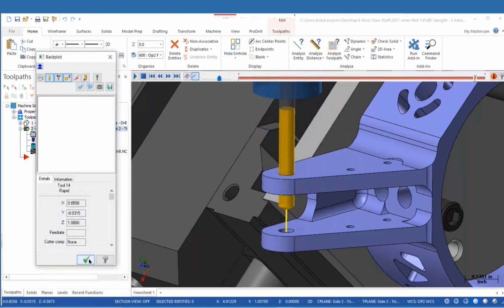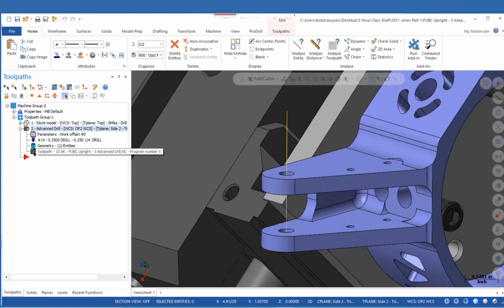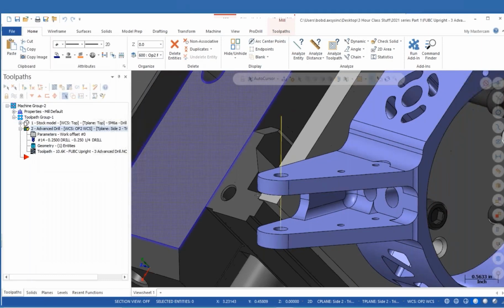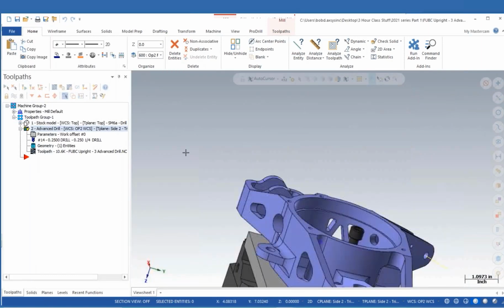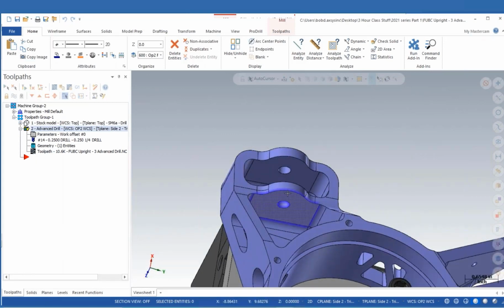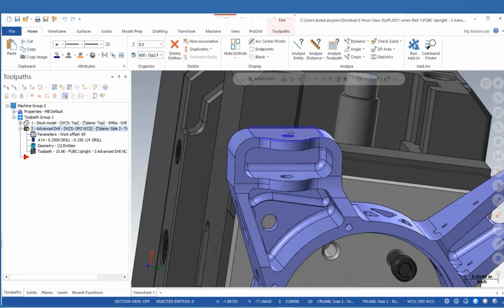I didn't show it before, but that other toolpath took roughly 30 seconds. With all the pecks removed in the center section, the air, we've reduced it to just under 12 seconds. It's quite an improvement. Where this is going to come in really handy is a couple areas. If we look at this part over here, we have no choice in this area but to do what we just did. We're going to drill it from this side through.